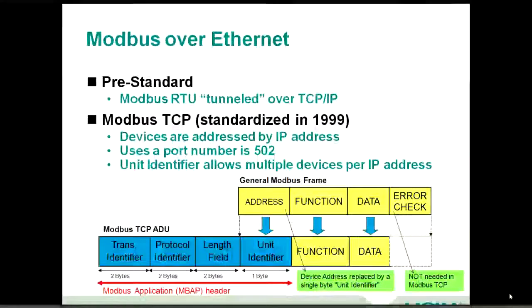And I think the exciting thing is that the Modbus protocol was a real simple protocol, and because of its simplicity, it made it easy to do some things. One of those things was some early adopters said, hey, we understand some of how this works, and there was some pre-standard things done by people that had a good understanding of Modbus and really had a good grasp on Ethernet and IP communications. And what they did was take Modbus RTU and just put it inside of a TCP IP packet and move it over a network.